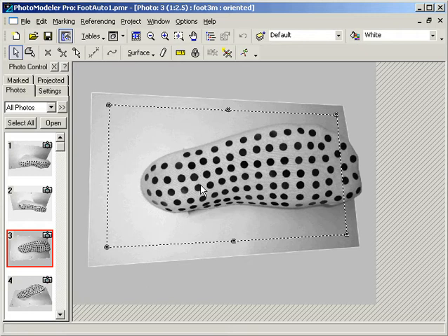These are useful in complex environments where there are other circular objects in the background that need to be separated out. Retroreflective targets are available from some survey supply companies or can be made out of material available at most sign shops. The third form of targets is projected targets. These are targets on slides that are projected onto the surface using a slide projector. EOS Systems has a number of dot slides available in different grid densities.